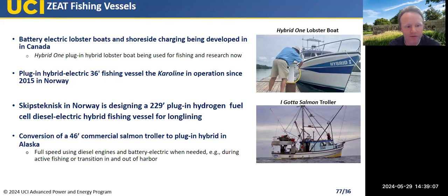And then in the US, there's a project looking to convert a 46-foot salmon trawler to plug-in hybrid in Alaska. That's a collaboration with the DOE. One interesting common activity pattern for a lot of these plug-in hybrid fishing boats is that they can use the diesel engines for full speed, right? So when they're transiting to the fishing grounds, for example, they can use the diesel engines. And then once they get there, they can switch over to the battery electrics while they're actively fishing.